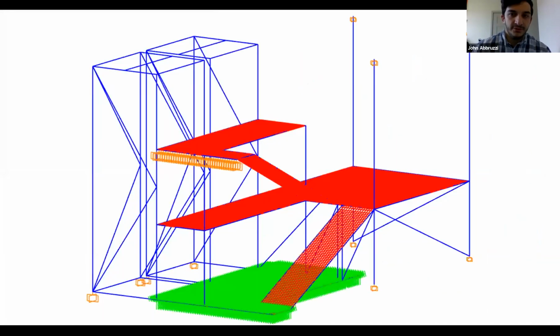This is a wire mesh view of the platform design with the joint restraints highlighted in orange and green. The orange represents fixed restraints that can also be used for floor continuation. Since the main floor of the Eccles building continues far after our design, fixed restraints were used to show this continuation. The green represents springs.